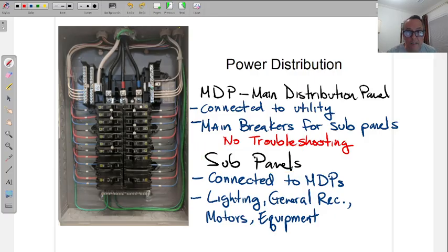Now, which one is it? Well, it's not the one with brown, orange, and yellow, because that's high voltage. So if you're standing in front of 4 of them, and 2 of them are 480/277, you can eliminate those 2 as the ones feeding your outlets, and now you're down to 2 panels. It's not the main distribution panel in here. I walked into the electrical room, there were 7 panels, and I've narrowed it down to 2.